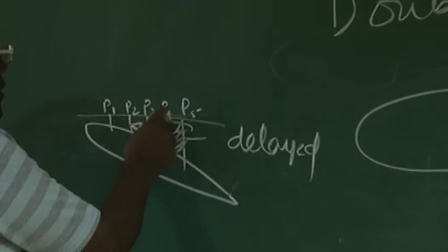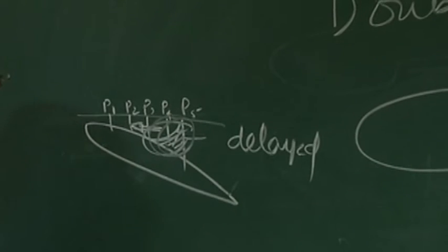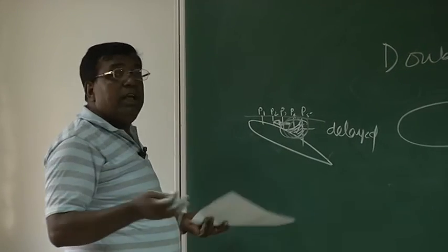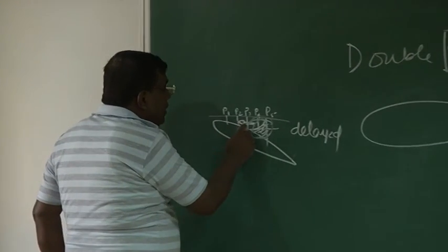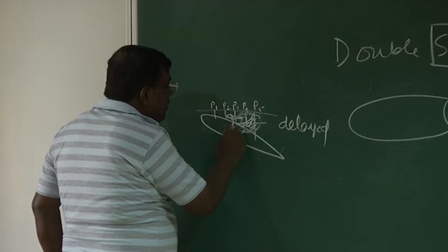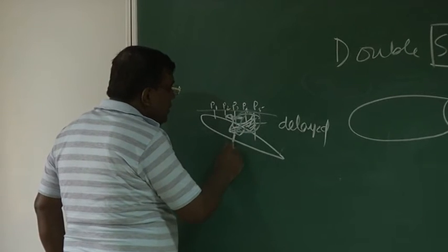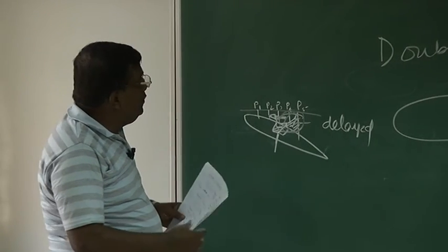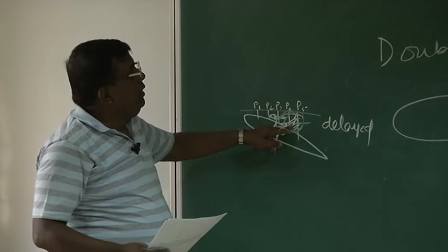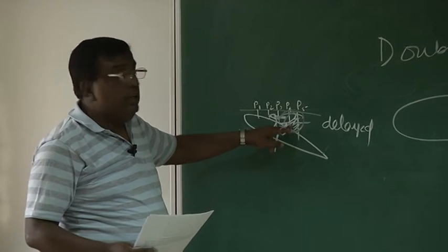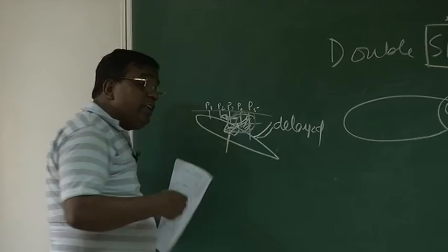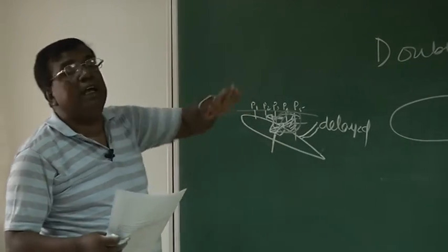If this friend of ours, the boundary layer, has a deficit of energy, I supply him energy. So what do I do? This is some fluid with high energy, I pump it into this area. That energy will revitalize this fluid particle, and this separation point may move from here to here. Effectively, I can further increase this angle.